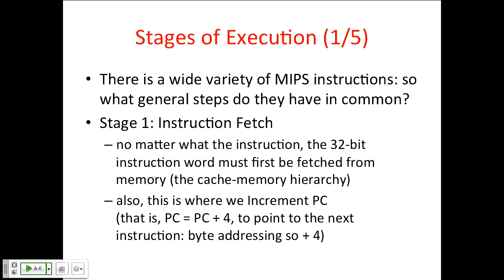How does it actually get the bits? So we'll go through that a little bit later, but basically, say you have a 32-bit address space like we do on the MIPS you're using. There's 32 wires that carry the address to the memory chips, and they decode those 32 bits to figure out which particular cells bits are stored in, then read the values from those bits and push them back on another set of 32 wires going back to the processor where it captures those values, right?